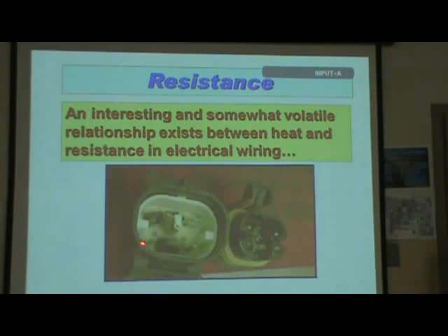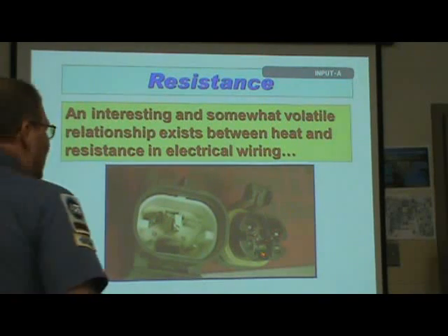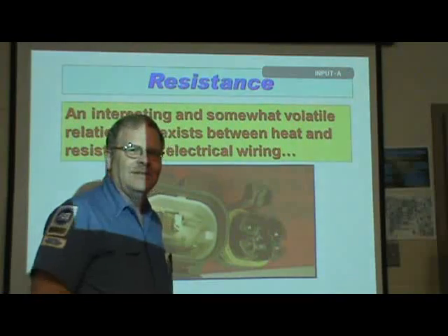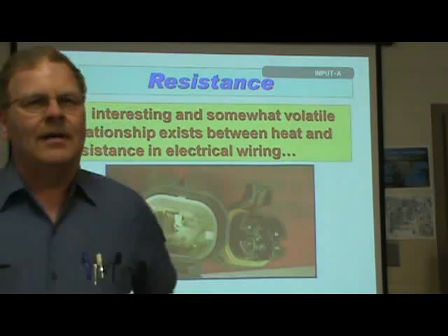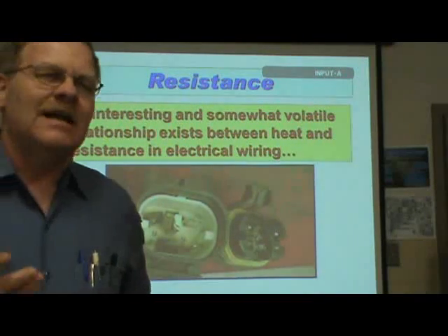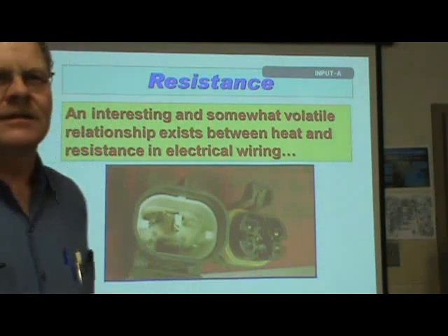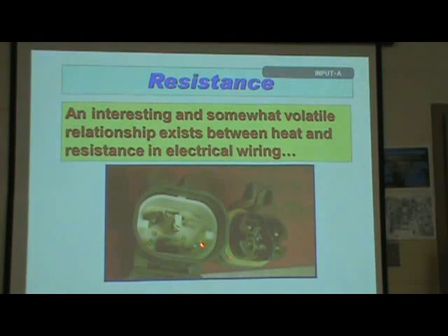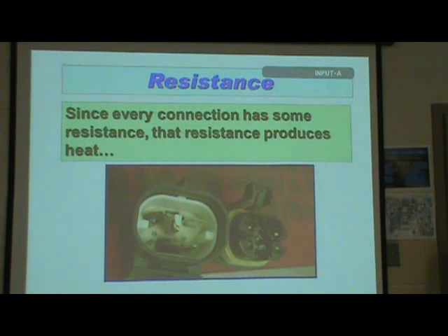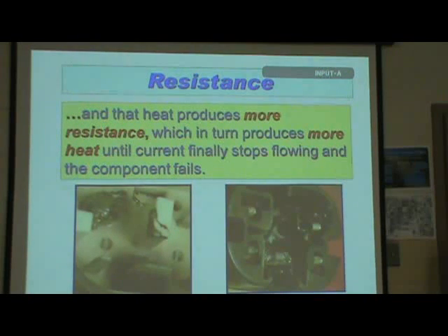And look at this. Anybody seen anything like that, where they burn up these terminals? It starts to develop oxidation, and that's resistance. That makes heat, and that makes more oxidation, and it just continues to heat up until you wind up with a nasty mess. Every connection's got some resistance, and that's a snowball effect.